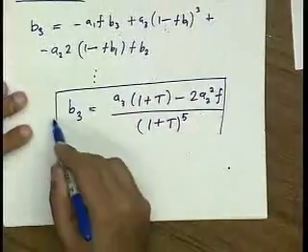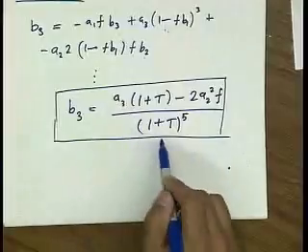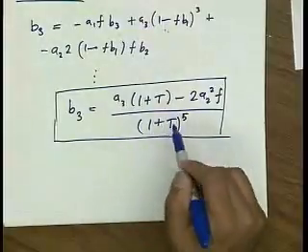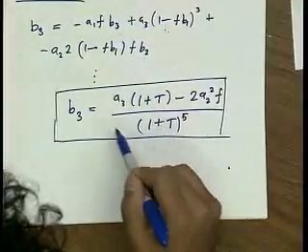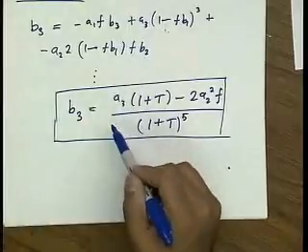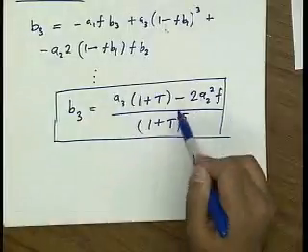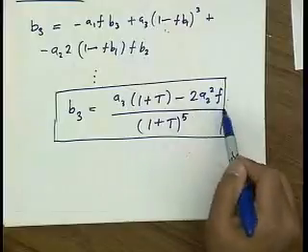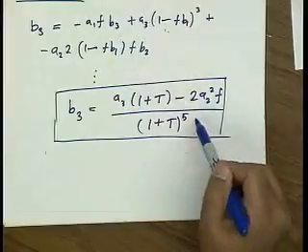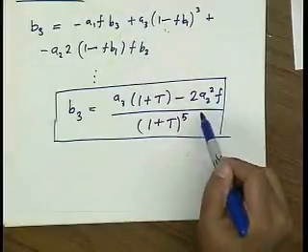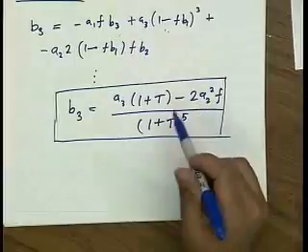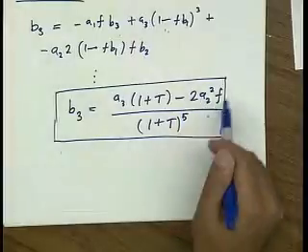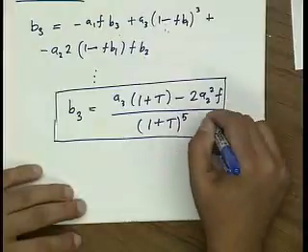The good news is that compared to A3, we can see that by 1 plus loop gain to the 4th power, we get a reduction. The bad news is this term, because this term actually introduces cubic order distortion in a system where you didn't even have it to begin with. This is called the second order interaction term.